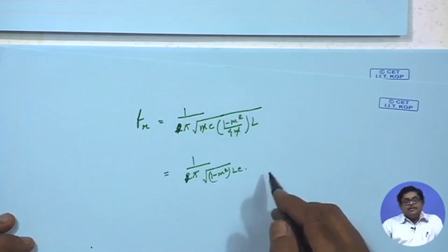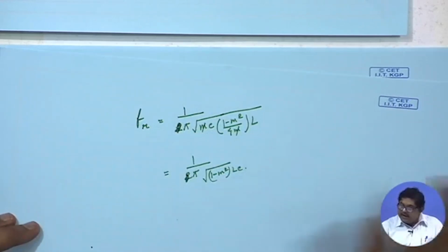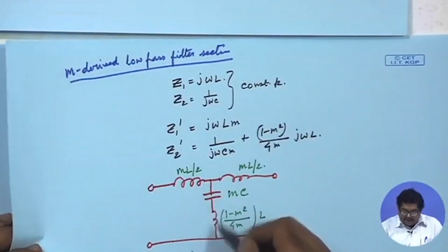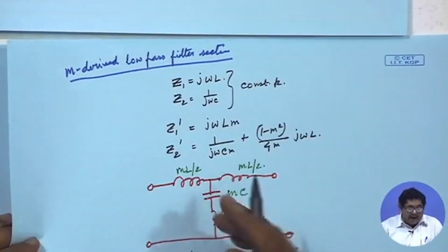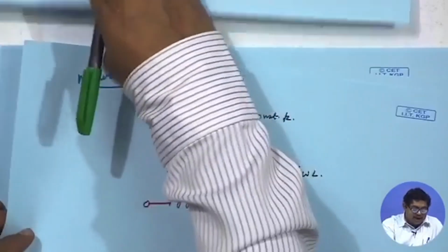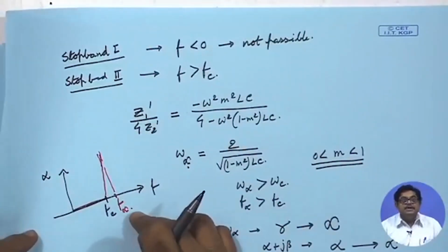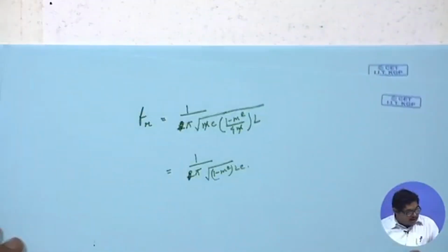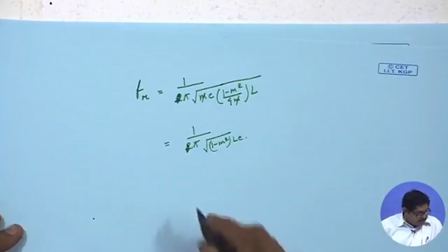That shows me that yes, physically that is the case. Since I have this series resonant circuit, I can make it resonate at f infinity, and by that I can put a very high attenuation in the stop band.